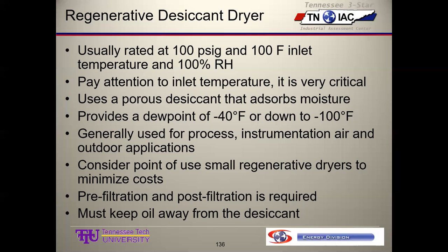Desiccants love oil. So if you've got a lube-injected compressor, you have to put really good filters to make sure that oil does not get to the desiccant. If it fouls it, then you get to throw your desiccant away. Oil and desiccant love each other so much. Once they come together, it's a union that you can't break. And so you throw them away into the trash bin of history, and you buy more desiccant.